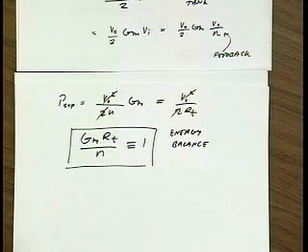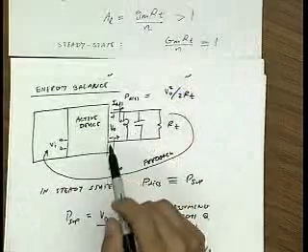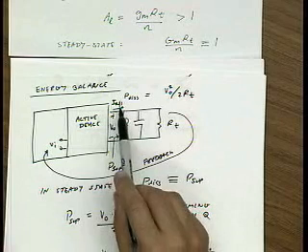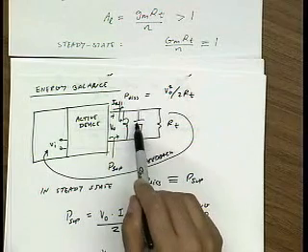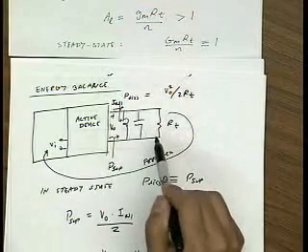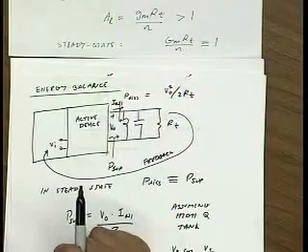Questions? Yes, David? How close is the voltage waveform to the ideal sinusoidal? Yeah, the way you can estimate how closely this is sinusoidal is you calculate how much power flows, let's say, in the second harmonic voltage. The impedance at the second harmonic is essentially 1 over 2 omega naught C. And compare that to RT, you can see how much lower the impedance is at second harmonic, and that can give you a way of calculating.